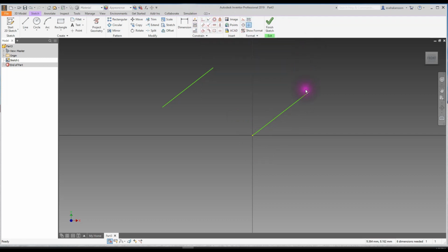You can use that for a whole sketch, not just a line. Let's say you have a sketch like this, and let's delete this line to get it out of the way, and I want to connect this corner here to the origin. You can just do it the same way. It will move the whole sketch, provided that it isn't connected to something else, and anchor it to the origin. So that's the first one. Let's delete this one for now.